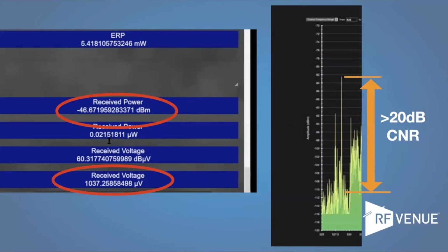And it changes. I think on one of our blogs, we took one of the RF Explorers, and your noise floor gets worse as you go up, right? So if you're working on the 27th floor, you've got more noise than if you're working on the ground floor, probably. We were testing a system in Boston and we were up on the 13th floor or something, and the noise floor was like minus 60. That's horrendous. That'd be a tough spot. But anyway, that's what you're shooting for.